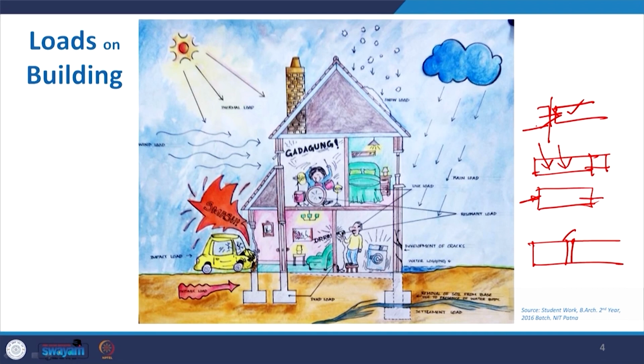Now, move on to the other one, not pertinent to the urban area, or maybe an area where there is no snowfall, but in some parts of the world, or even in India, some areas where we have to take care of this, because that is an additional load, but again it is not permanent. Permanent means in a particular season we will get this additional load, it will accumulate on the roof, and it creates additional load.